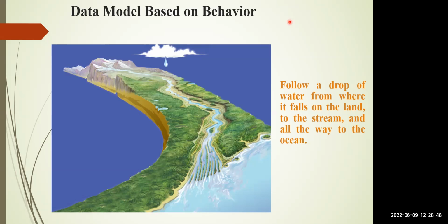This is basically how things work for the data model. If we have some rainfall here, how that drop can be followed by different flow, and then it will go from the stream toward the river and the river toward the ocean. So how those types of flow will work, for example, we have some mountainous area, so we can here find some slope using the digital elevation model. That basically gives us the height of any area. It's up to some pixel, like the 30-meter resolution. So basically, I hope you got the idea about the resolution of the pixel.